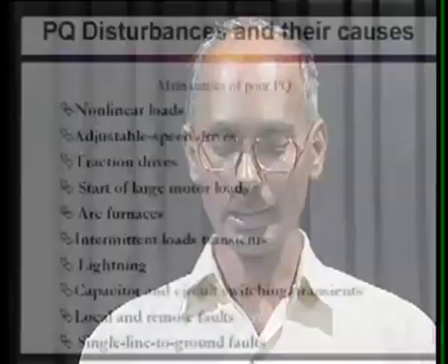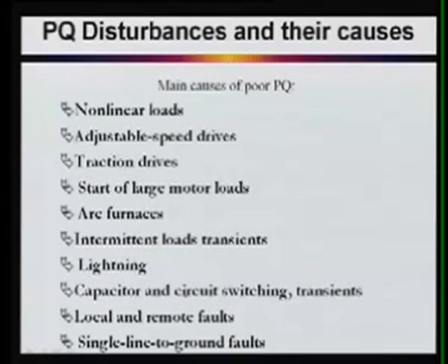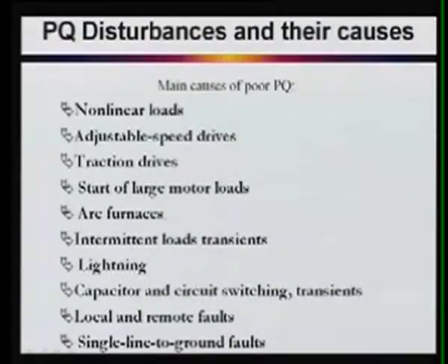If you are starting a large motor, what will happen? They require a huge inrush current, and that is rich in harmonics. Therefore, if a sudden huge current is flowing, that creates a lot of power quality problems in your supply system. Arc furnaces also introduce power quality problems.